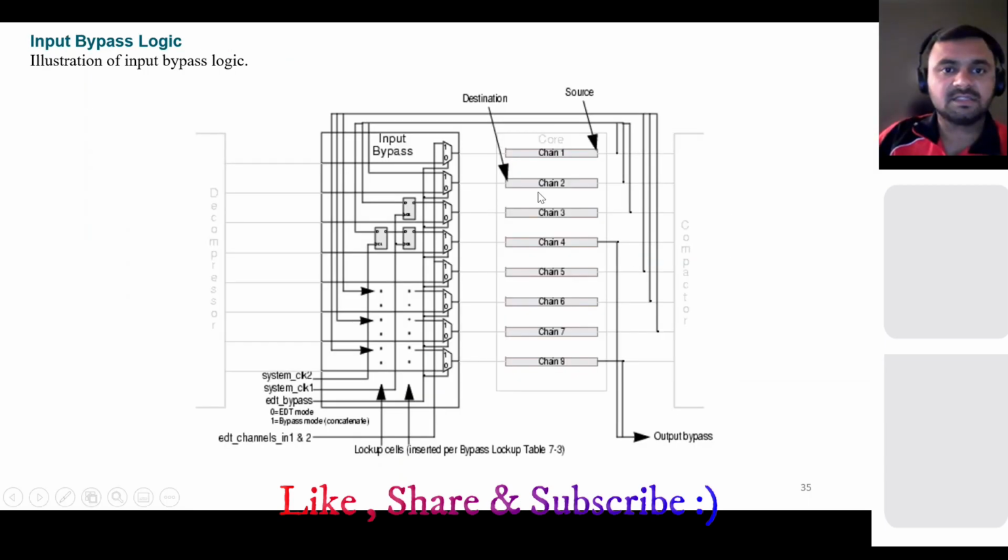Then the third one is the bypass. You bypass your internal chains. Basically, if there is a problem in the decompressor or compactor side, or a problem in your chain itself, what you do is take the output from each of the chains. You have 8 chains here. You take the output of that chain and concatenate it with the second chain.